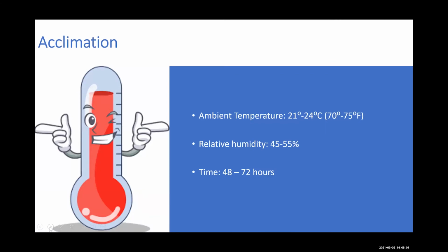The reason laminate needs to be stored flat for 48 hours is because it needs to acclimate to the environment where it is going to be worked. HPL and the substrates it will be applied to are paper products, which will react to humidity. When humid, laminate will expand. When dry, it will contract. The acclimation process lets the millworker know that the laminate and substrate are not reacting in opposite and drastic ways.